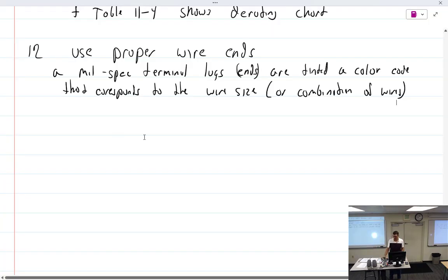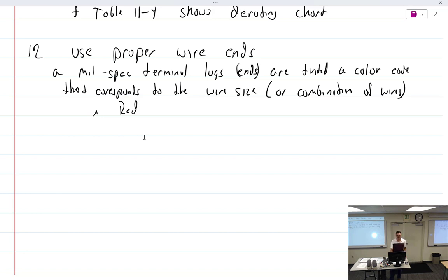All right, so what about a switch? What about a switch if you have a double pull, double throw? I stick with 4. I never go more than 4 things on either terminal. That's my personal rule, because that's the only rule that I'm aware of, and so I never violate that one. It's 4 to a plug. So do you go all in the same ring terminal, crimp the ring terminal around all 4 wires? I don't like to do that. I would do 4 different ring terminals.